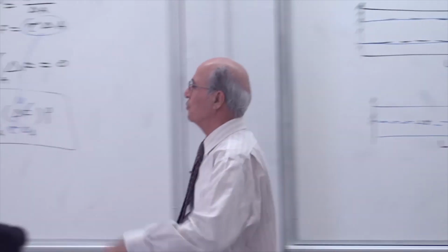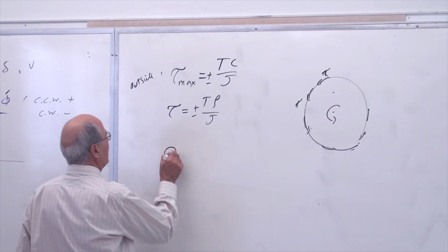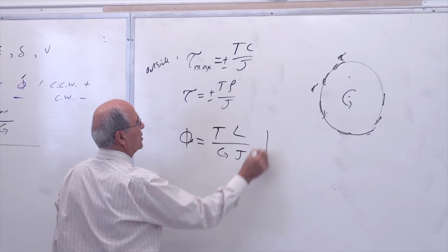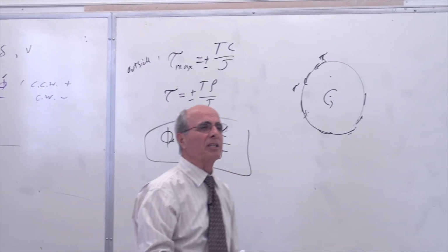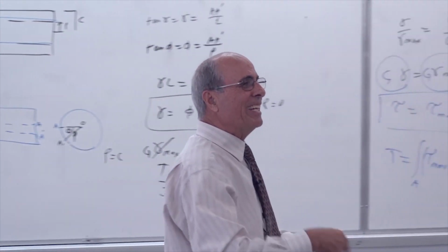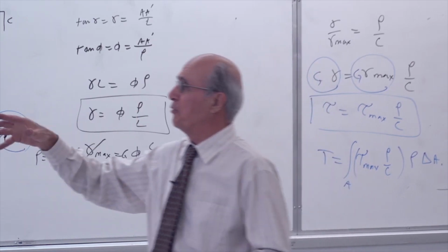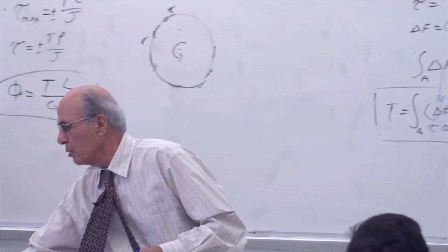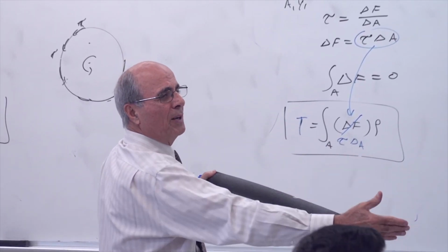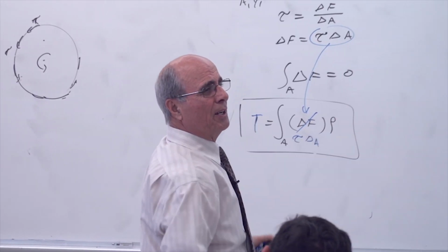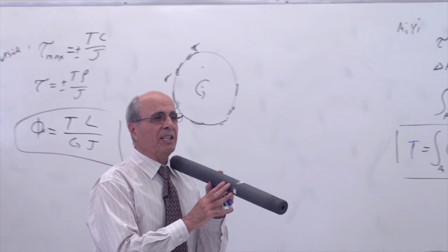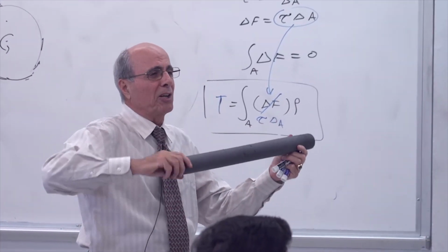Everybody said that. You don't have to prove that. It is there in your handout. So phi, which is the angle of twist, becomes TL over GJ. Exactly like delta. Look how similar that is to delta. Is that correct or not? Delta was PL over EA. Now everything changes to a different format. Phi depends on the value of the torque. Look, guys. The more torque I put, the more phi I have. Yes? Depends on the value of L. The more L I have, the more phi I have. Everything is there like before. What is the G? G is the modulus of?